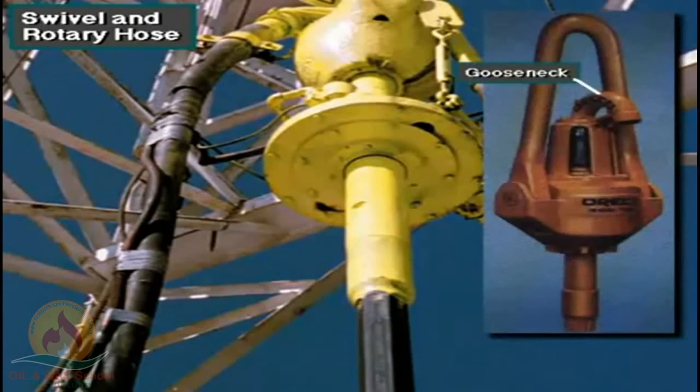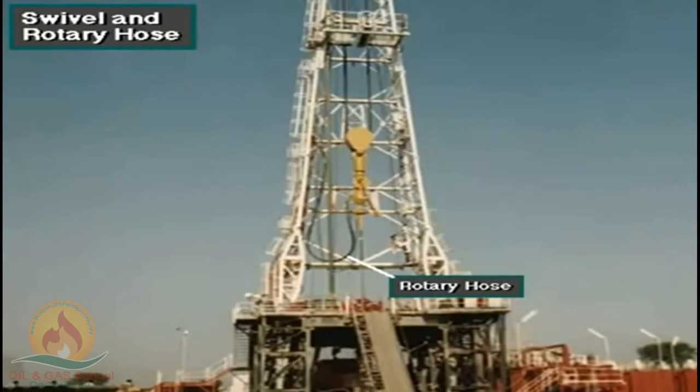At the same time, the rotary hose conducts drilling mud into a curved pipe called the gooseneck. The gooseneck attaches to the swivel and carries drilling fluid to the swivel via the wash pipe. The rotary hose is flexible, steel-reinforced hose that allows the swivel to move up and down within the mast. A passageway inside the swivel stem conducts the high-pressure drilling mud into the Kelly and drill string.